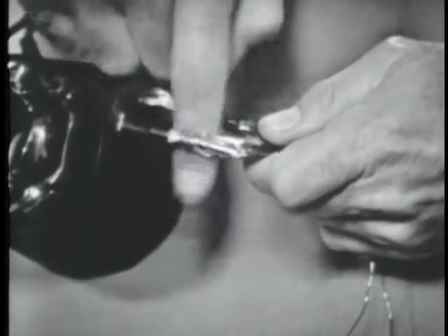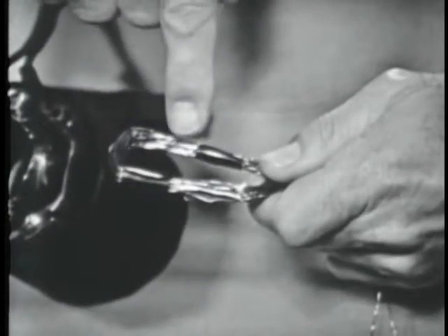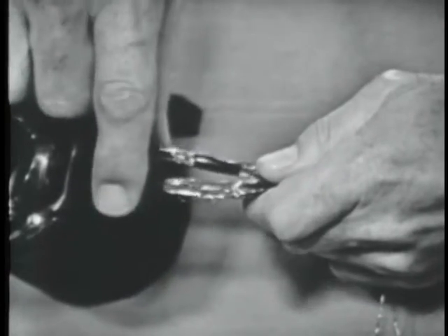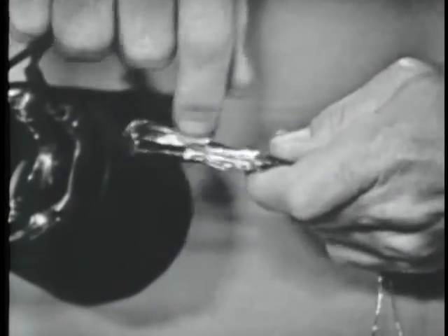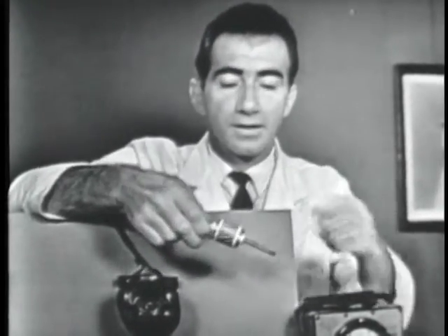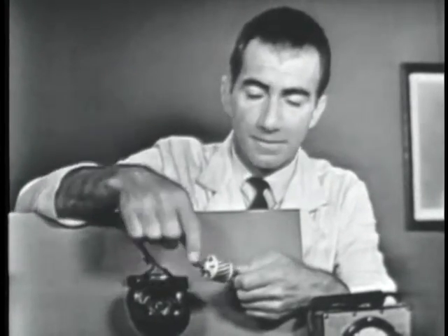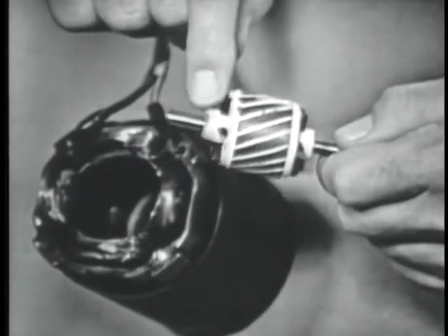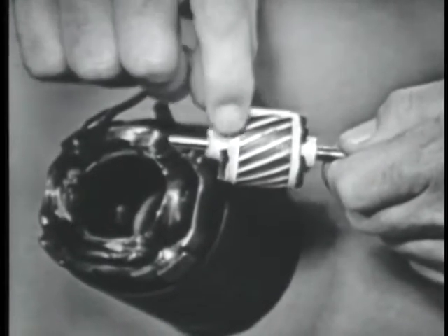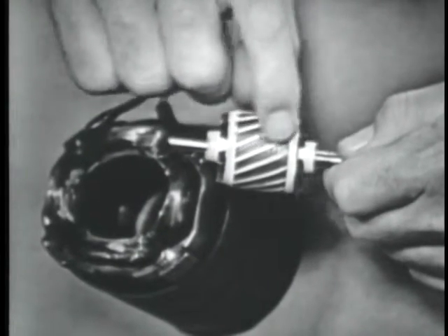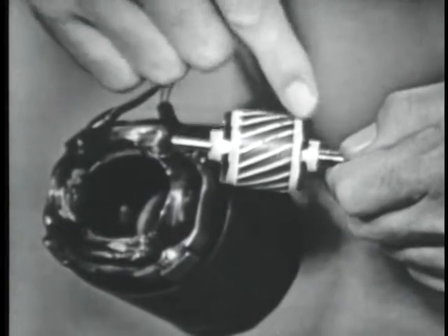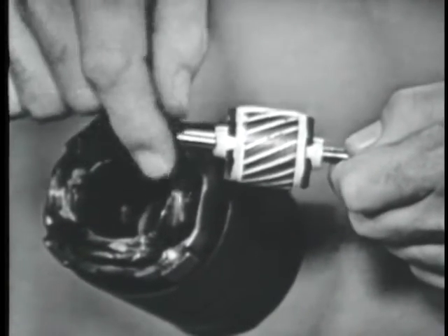Now this means that we'll exhibit a north pole on one side and a south pole on the other. Or in other words, we have magnetized the loop, made it an electromagnet. Right, an electromagnet. Now actually, the rotor is the same thing, or almost the same thing. A rotor is made in a very, very similar way. Instead of using windings of wire, however, we use a conducting ring on this end, a conducting ring on this end, and they're joined together by conducting bars, these little white lines. Sometimes they're made of copper, sometimes aluminum. This one happens to be aluminum.